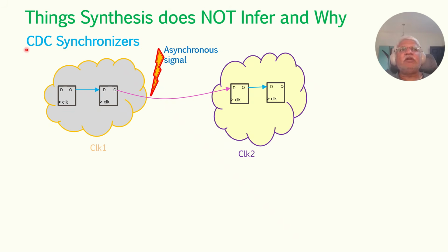This is called clock domain crossing, because it is crossing from one clock to another clock. That is why, to stabilize this asynchronous signal which is originating from here, you need a synchronizer. Then you will be transacting and giving it as a synchronous signal to this clock domain flip-flop. Okay, so this action is performed by a synchronizer. We will figure out why this whole thing is needed.